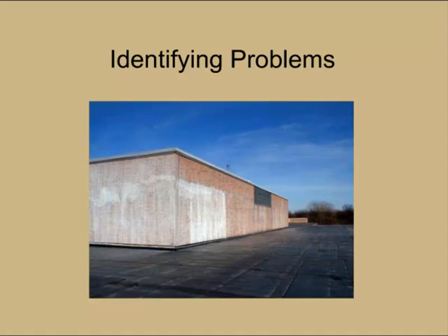So he sends them out. They come back with Thompson's deck sealer, similar to what you might apply on your deck near your pool or coming off the back of your house. And they applied it to the wall system, suffocated the wall system, didn't allow that wall to breathe, trapped all the moisture in there, created more harm than good. It created significant problems, and that's just an unfortunate consequence there. Required full restoration of that building to correct these issues.